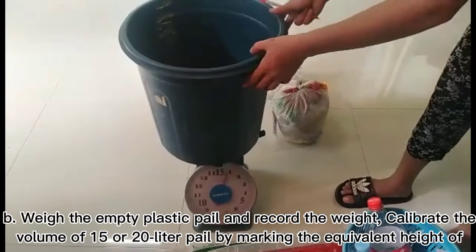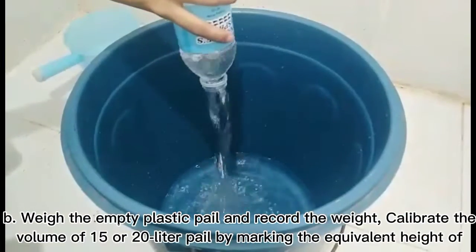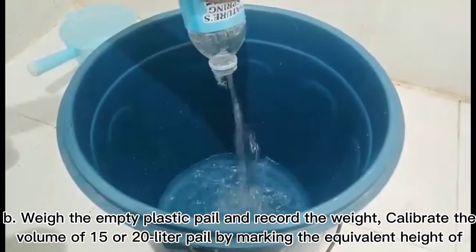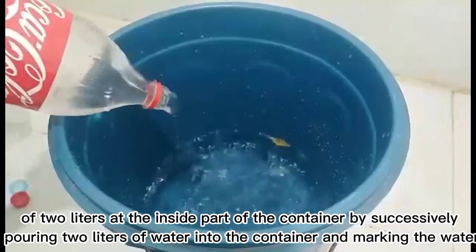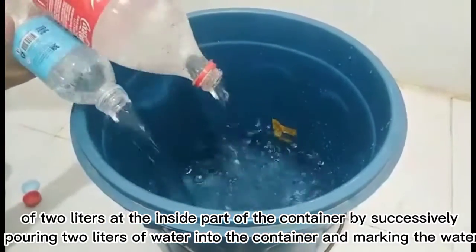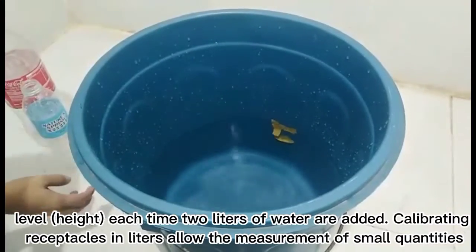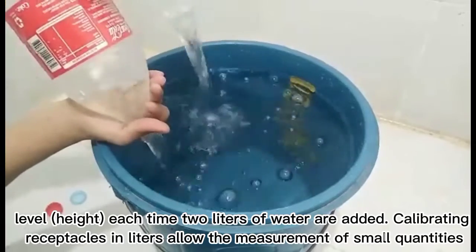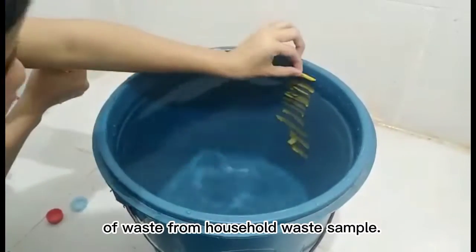B. Weigh the empty plastic pail and record the weight. Calibrate the volume of 15 to 20 liter pail by marking the equivalent height of 2 liters at the inside part of the container by successively pouring 2 liters of water into the container and marking the water level or height each time 2 liters of water are added. Calibrating receptacles in liters allow the measurement of small quantities of waste from household waste sample.